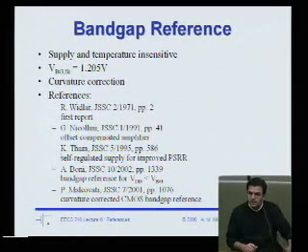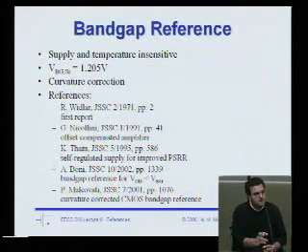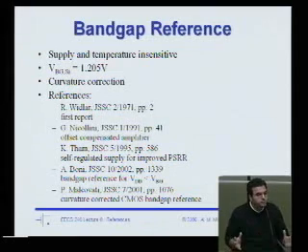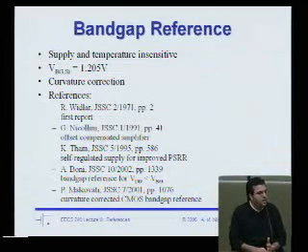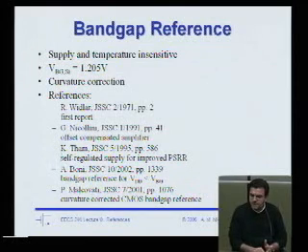But the beauty of it is that you have a circuit that is somehow fundamentally generating a voltage, which is the actual band gap of the crystal. It's pretty exciting. And that also means that because the band gap is relatively universal, right? Anybody who builds a silicon crystal is going to get the same band gap with the same purity levels, right? Then this is actually a very good reference. It doesn't depend on supply. It doesn't depend on temperature. Well, it has a weak temperature dependence. But besides the temperature dependence, it's a pretty universal voltage.